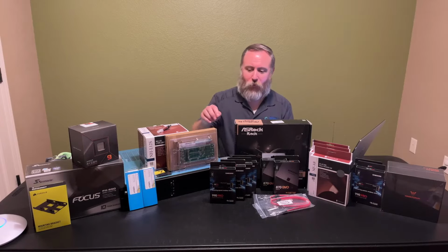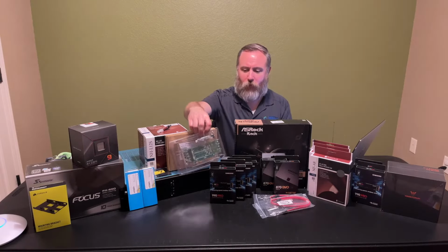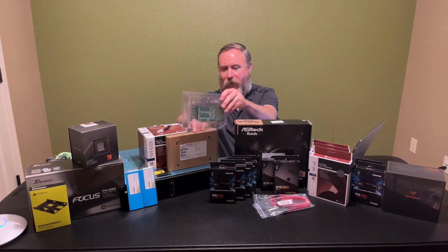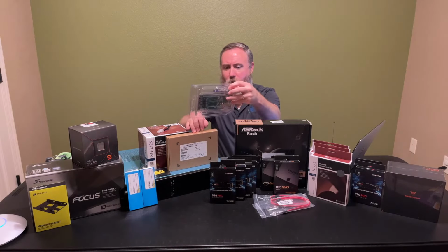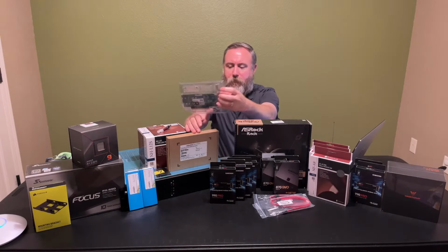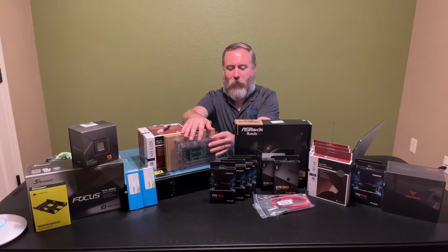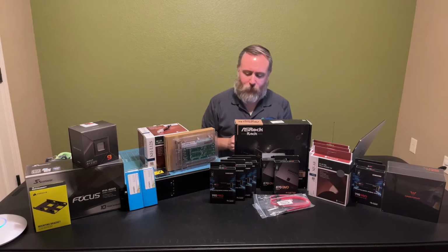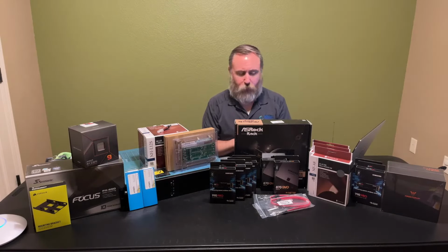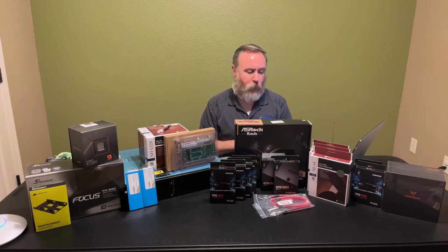And so this particular riser card here, and we'll talk about that in just a moment, allows you to have two NVMe drives on this side and two NVMe M.2 drives plugged into the back as well. And they all have their own dedicated 4 lanes to the motherboard and to the processor. Those are direct-to-processor lanes.